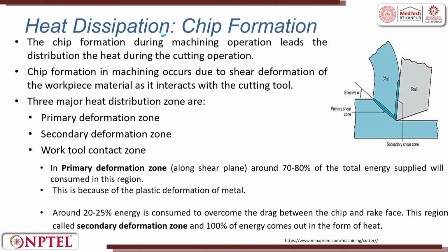So, heat dissipation in chip formation. When we take an orthogonal cutting, the cutting edge is perpendicular to the direction in which the chip moves. So here we are discussing orthogonal cutting. In orthogonal cutting, the cutting edge is straight and this is the workpiece. Now the chip moves on top of the rake face. When the chip moves on top of the rake face, it is metal to metal contact. So there is going to be friction.